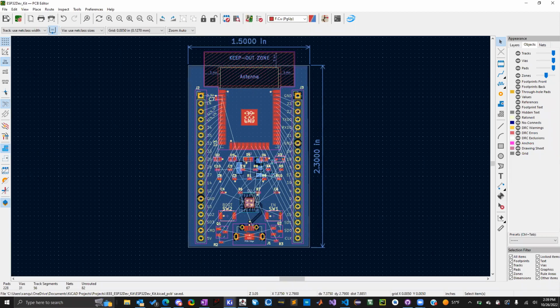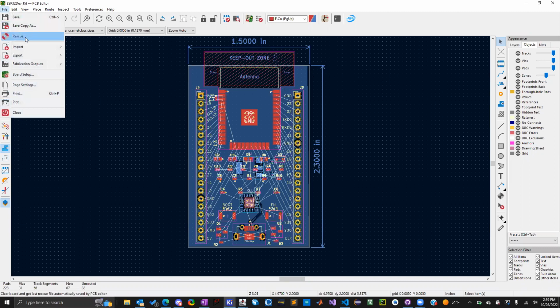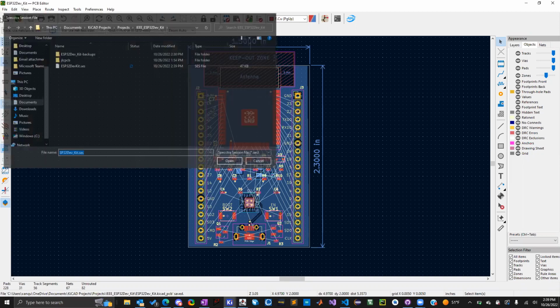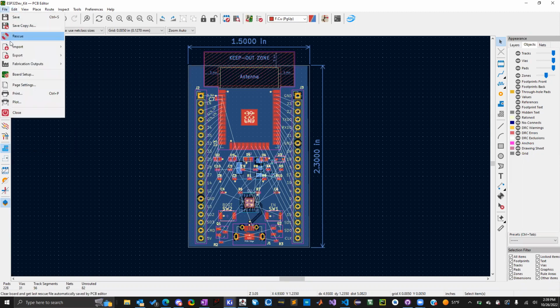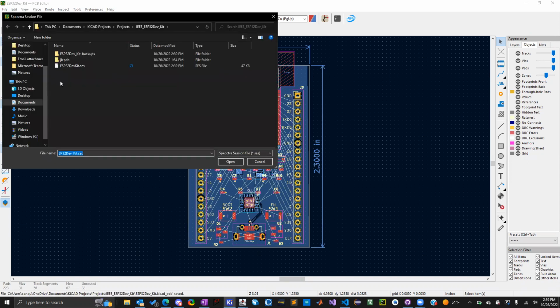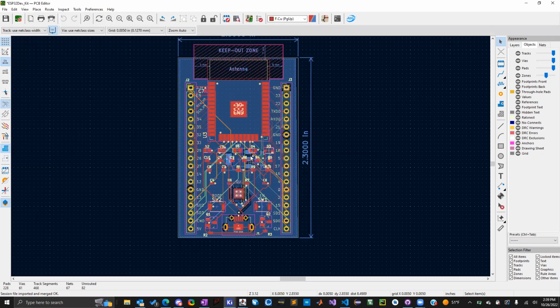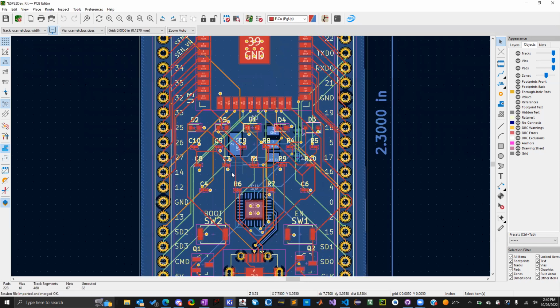So when you export that Spectra file, it automatically saves the Spectra session over what we had in the File Explorer. So I'm now going to go to File, go to Import, and import a Spectra session. And I'm going to select that one we just did. Click Open, and there's all our connections.